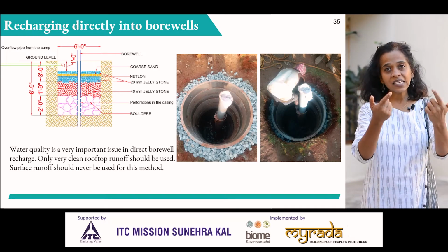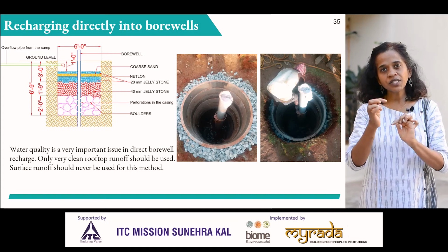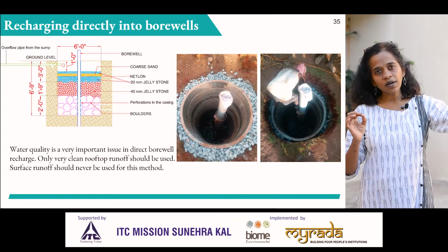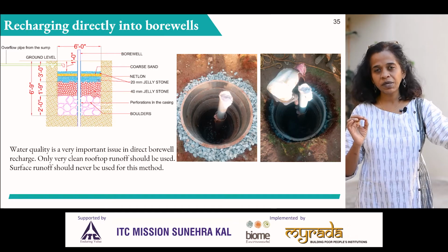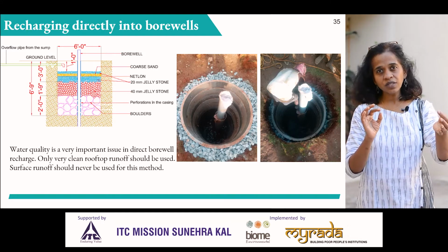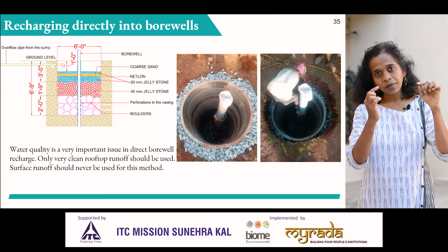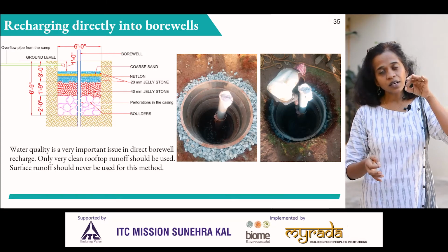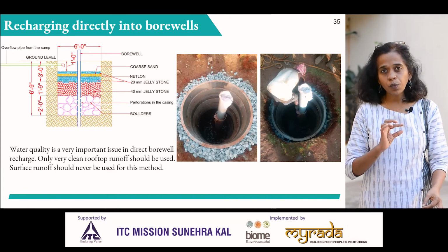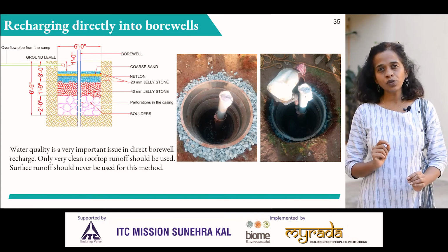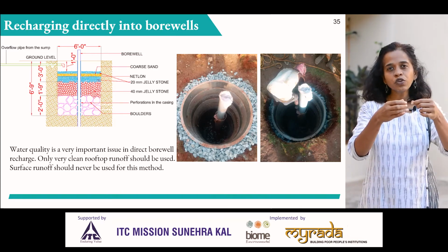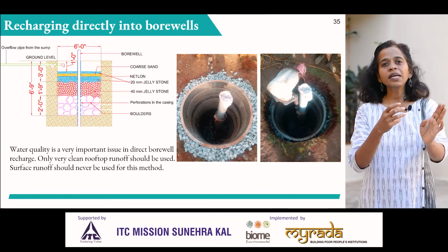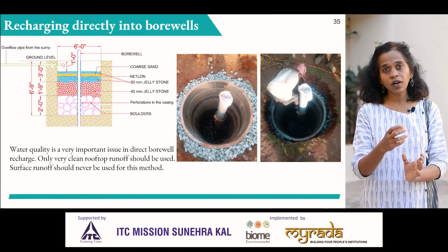We make perforations in the borewell casing so that the water, once it comes through the channel, falls into this pit, filters through these stones, goes through these perforations in the borewell casing to the deep aquifers from where this borewell used to be able to draw water. Some of the things to keep in mind: when you make perforations in the borewell casing, make sure that you wrap it with Netlon mesh.